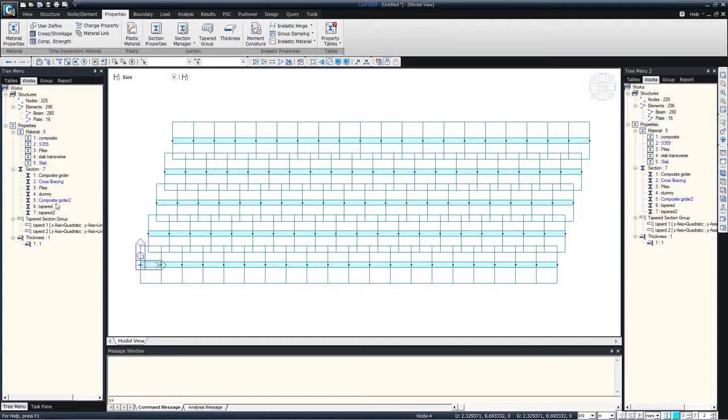And also you need to define those sections separately with a different name. Right now, coincidentally, I want the tapered sections to be cracked, so they are already separated out from the main sections. You can see that's the main section highlighted, tapered 1 and tapered 2. So I want tapered 1 and tapered 2 to be cracked.